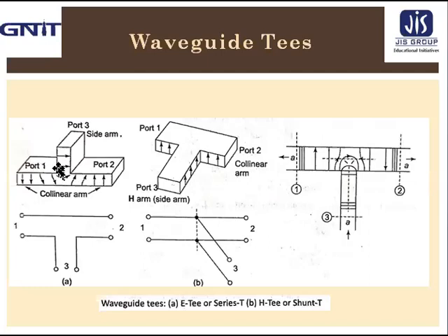Now, because of the junction, waveguide T's are poorly matched devices. Adjustable matching reactances can be introduced by means of a tuning screw at the center. Because of symmetry in structure and absence of nonlinear elements in the junction, the S matrix is symmetric.